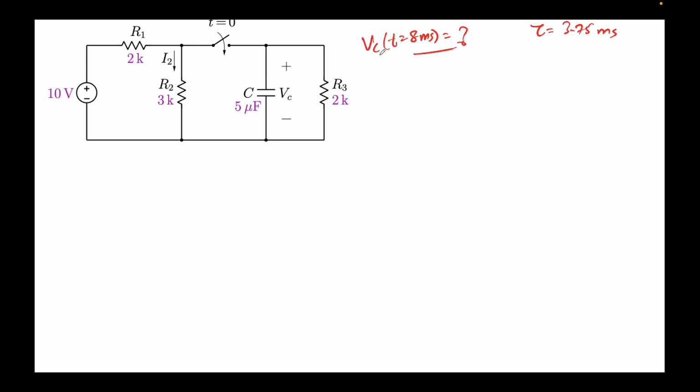Since we are required to find Vc as a function of time, and if you recall before, it can be written in this form. This is the most general form for an RC circuit, with the other sources being independent. So you can just take this expression, and what we require here is that there are two constants, right? So we need two boundary conditions.